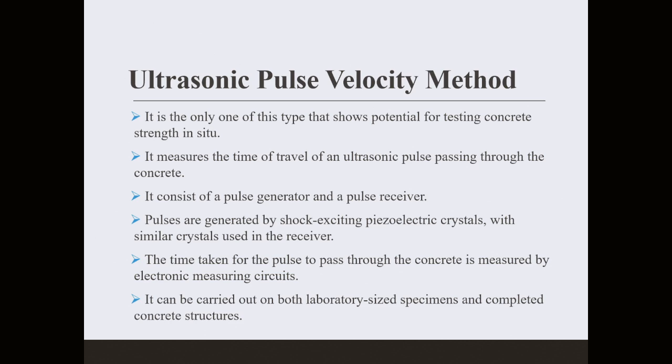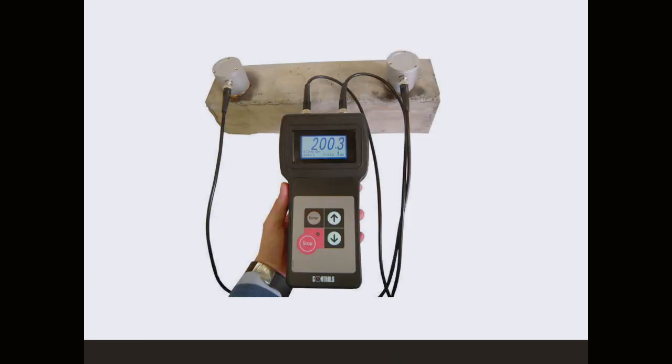Right now, by ultrasonic pulse, they can basically tell if the concrete section is still there, or you have excessive cracking, or spalling has happened, or even steel is corroded, through the speed of pulse propagation through the section. So you can basically tell what's going on even without seeing, because of the cast or the stay-in-place metal forms.